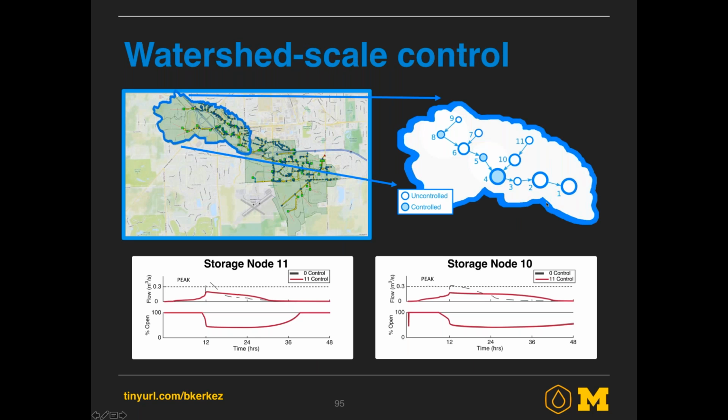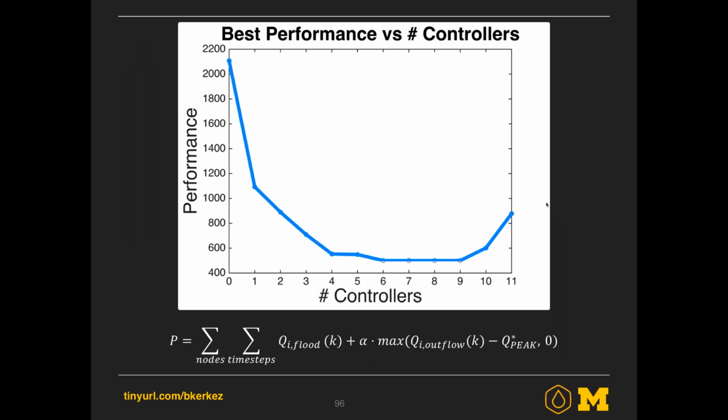So you tell us how many valves you need, and we can basically put them in there in simulation at least. I mean, we're obviously not there yet in real water systems. And so what we can start doing with these simulations is showing what's actually possible. Like how many valves do you need? Obviously, we don't need to valve every single part of the watershed. And what we're showing through some of our preliminary studies is that if you take a watershed that might be 2 to 5 square miles, oftentimes you only need 2 or 3 valves before the benefit of the valve starts decreasing.